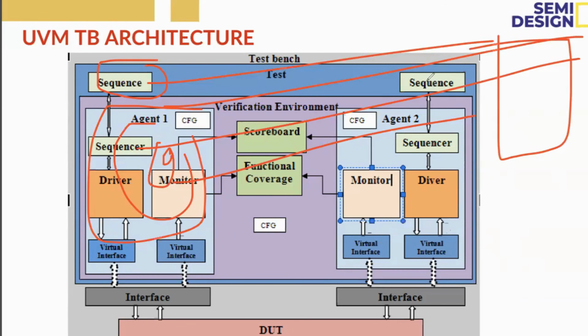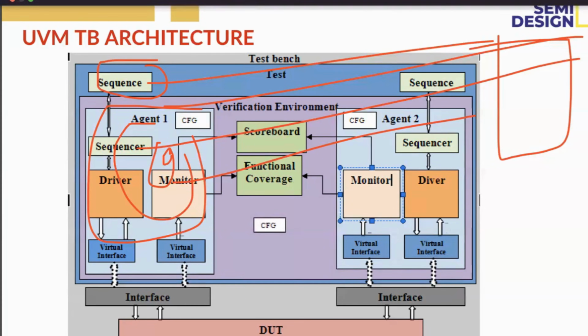Is it clear? Yeah, so every time I need to use the virtual sequencer to drive all the agents. Yes. But if my test scenario requires only driving one agent, that has to be separate. Then you can generate a separate sequence. Okay. Yeah.